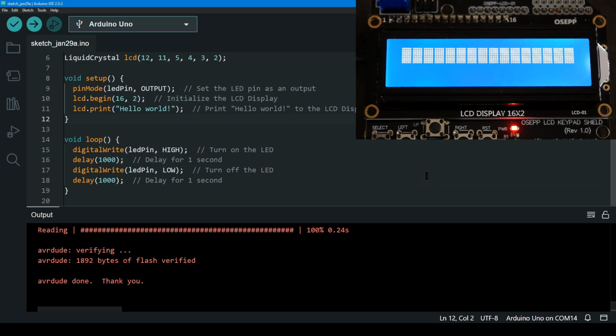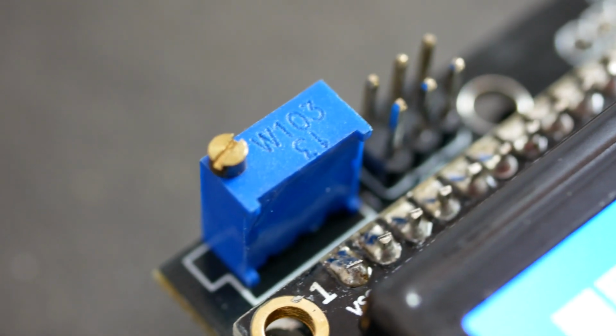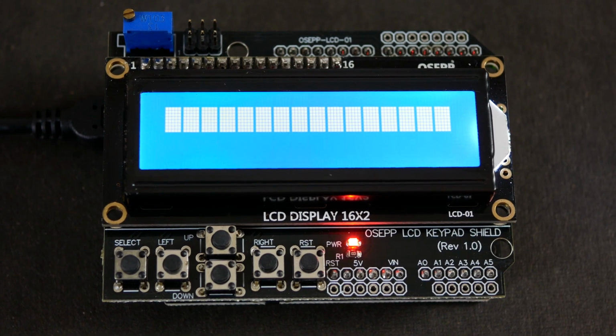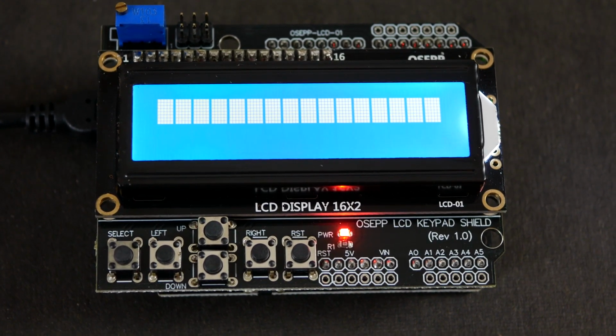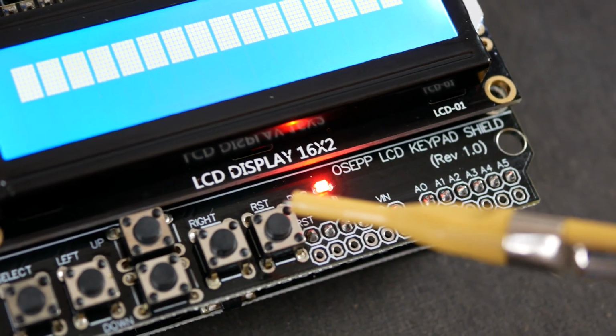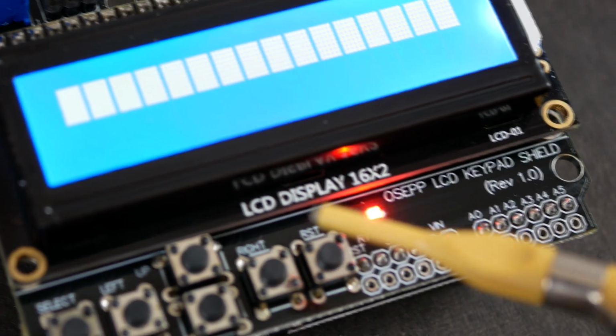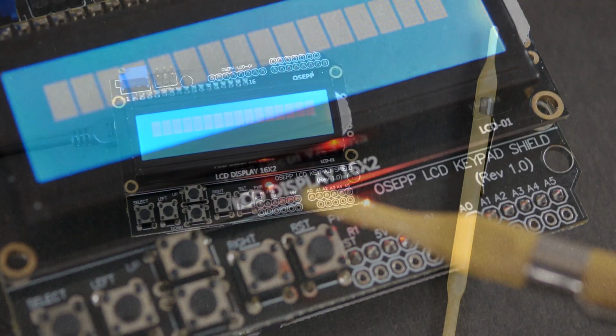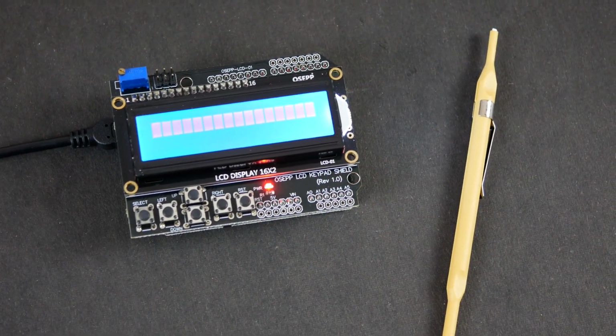At this point I remembered seeing the blue variable resistor on the board. Sometimes the LCD requires fine-tuning, and if the contrast is set too high, you are only going to see filled pixels. I retrieved an adjustment tool from my toolkit and adjusted the contrast up and down. It did not fix the problem.